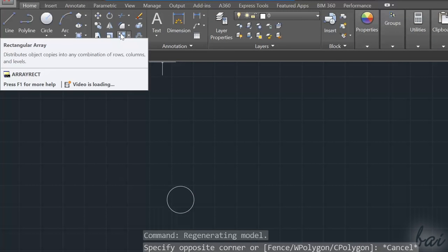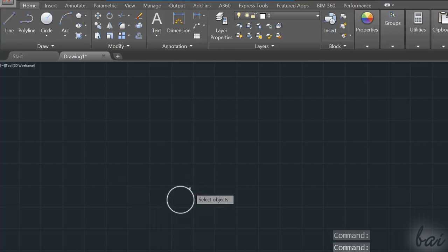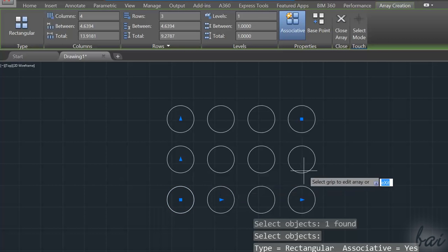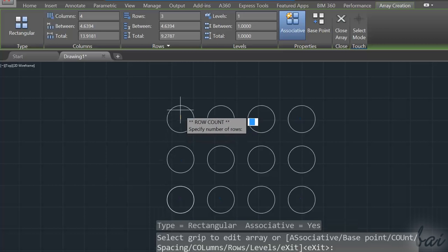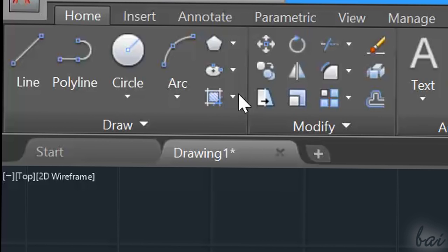To make arrays of a selected object, use the Array tool. For example, the rectangular array distributes copies of the selected object along a rectangular array, whose columns and rows can be fixed by using its blue nodes. Let's see how to fill 2D objects.